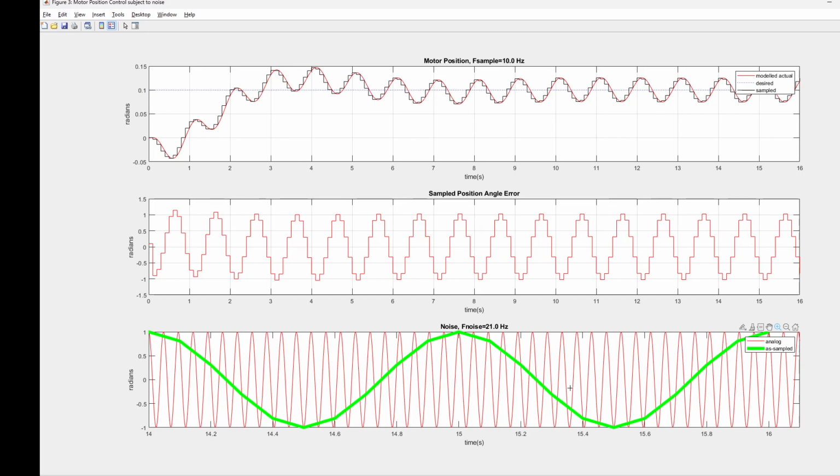Here we see the severe effect it can have in a feedback system if we are not filtering out components that are over half of our sampling rate. Again, we would need a low pass filter here of 5 to eliminate it. We don't have frequency components there, so we wouldn't actually need that filter. What we'd actually do is just sample at a higher rate, 50 hertz, 100 hertz, and then we'd have an easier job of designing an anti-aliasing analog filter on the input to the sampler.